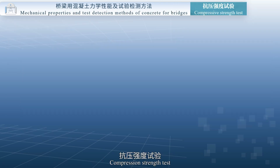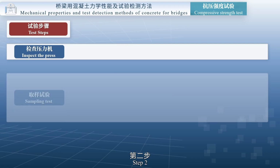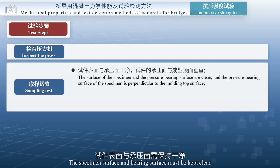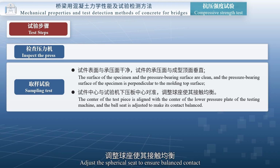Compressive strength test. Test steps. Step 1. Inspect the press. Step 2. Sampling test. The specimen surface and bearing surface must be kept clean. The bearing surface of the specimen shall be perpendicular to its formed top surface. Align the specimen center with the center of the testing machine's lower platen. Adjust the spherical seat to ensure balanced contact.